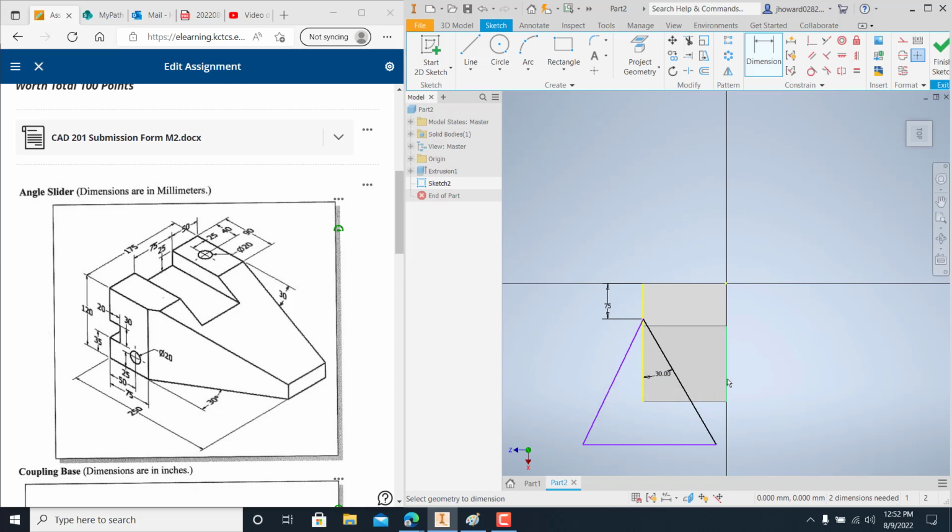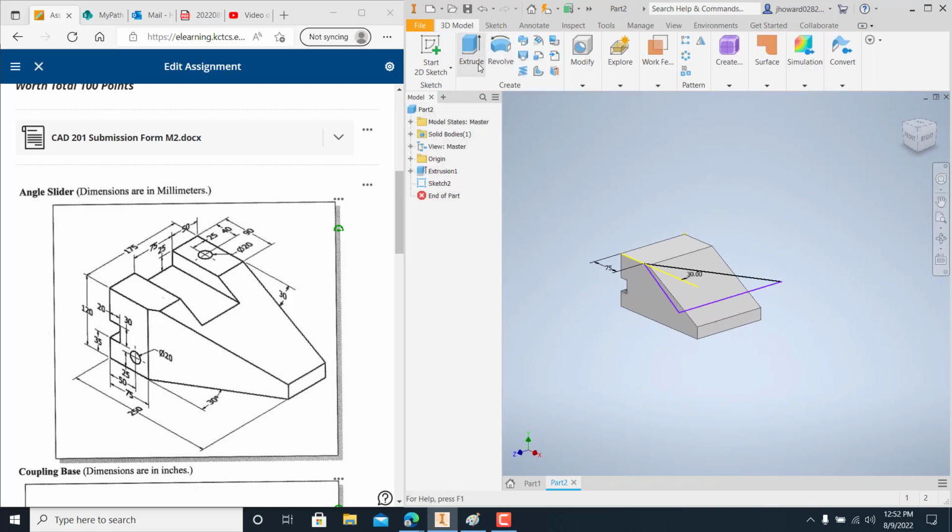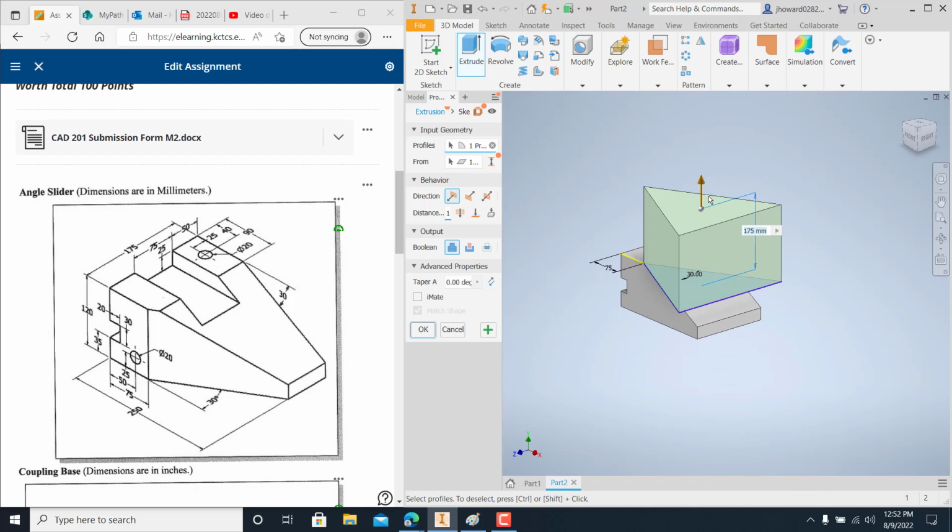And that's it. You're like, what? What do you mean that's it? I just need an enclosed area so that I can do an extrusion to cut that out. So now I'll extrude this. You all see what I'm saying? When it goes up, you see it's green, it's wanting to join, but when I do a cut, it automatically turns it, and you see that reddish look. It's telling you that's cutting, and I'm going all the way through.